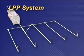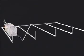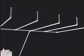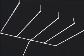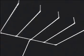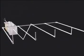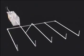Now, let's go through the steps in setting pump requirements for the other type of system we'll be treating in this presentation, a low-pressure pipe system. Once the parameters have been determined, actual selection of the pump is essentially the same as in a step system. In LPP systems, effluent at low pressure is delivered evenly throughout the dosing field. The distribution network consists of small diameter pipe with evenly spaced small diameter holes.